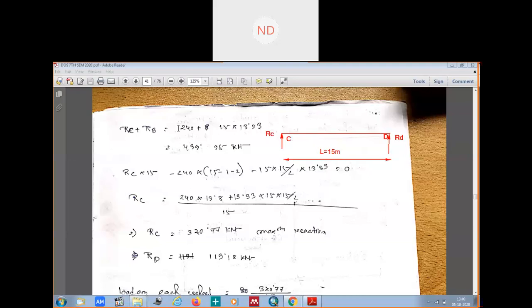This is the crane. We will have the trolley. The trolley had a minimum approach distance, that was in your question. It was 1.2 meter. Now this distance is 1.2 and the load here was given to be how much? 240. We had just now calculated the crane load plus the trolley load, 240 kilonewton, in the first step.